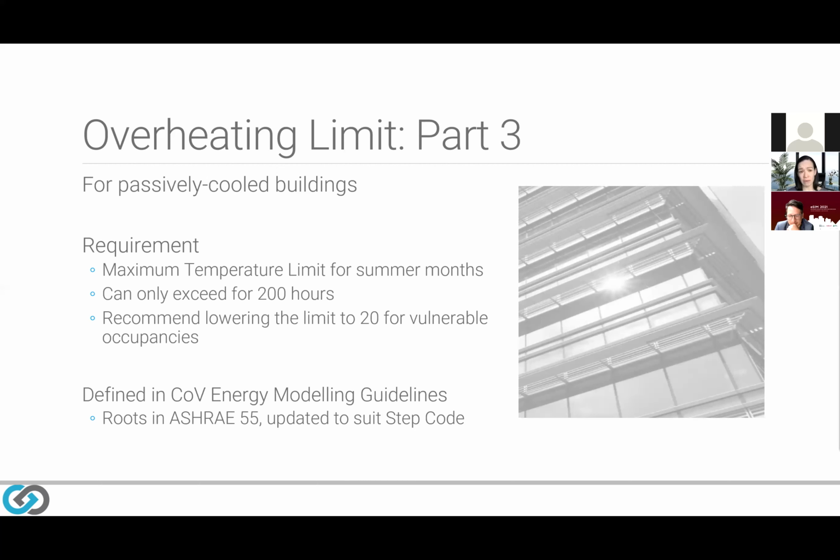And so some developers and owners are choosing to adopt that lower vulnerable occupancy target across the board as well, such as BC Housing. All their projects require only the 20-hour limit to be met. I won't go into details on the calculation, but it's defined in the Vancouver Energy Modeling Guidelines, which apply to the step code. And it has roots in ASHRAE 55, and then it was updated to suit the step code.